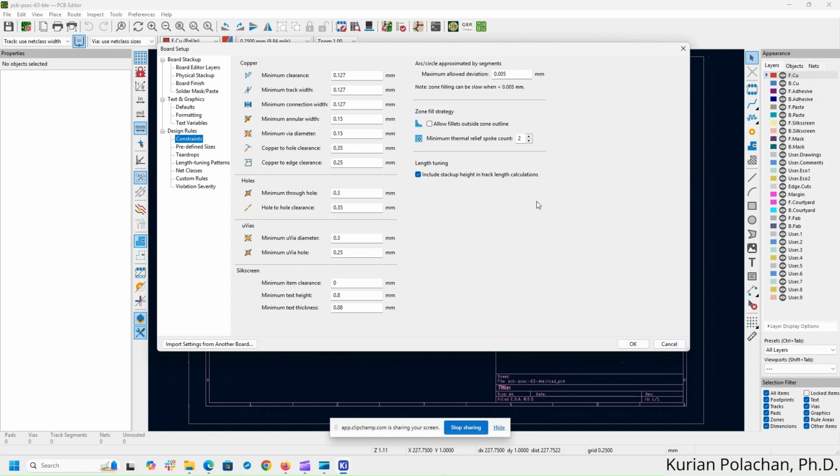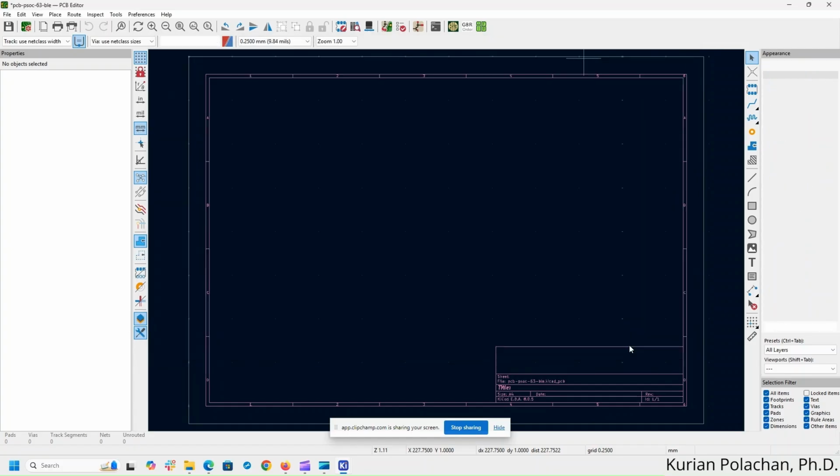So, if you are not sure about what constraints to fill in, you can copy paste the contents that is shown here, or you can also go to the PCB fabricator website, get these details and populate it here, or you can send a mail to the PCB fabricator and get the details from them so that you can fill it in the KiCad board setup constraints window. Now, once that is done, click OK. So the board is set up, the constraints are given.